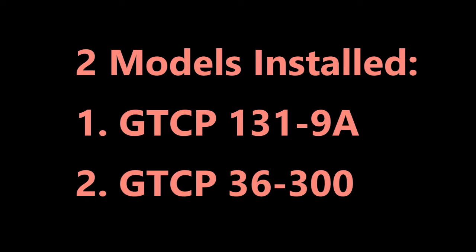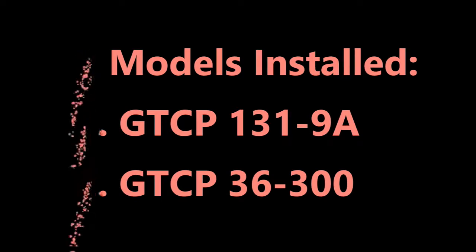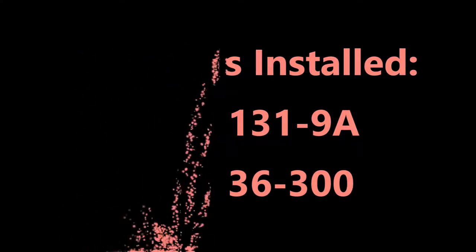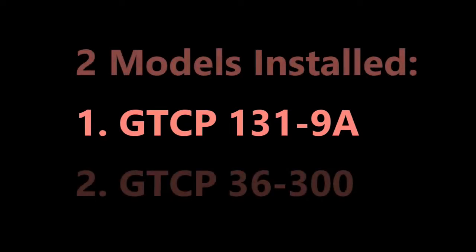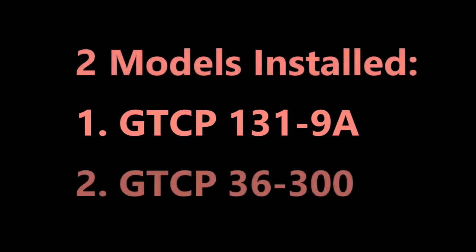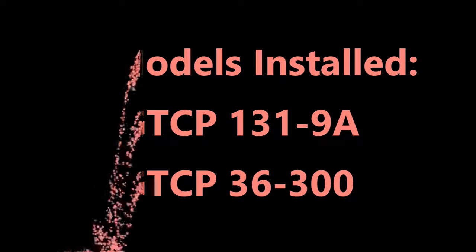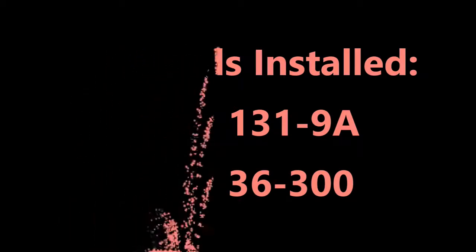And as far as the A320, it's actually installed on a certain range of variants on the A320. Okay, that's actually between 3270, I believe, and 3271 to 78. Those are actually shown on the airplane. So when you see those numbers, or see that it's a number within that range, then you'll know that the GTCP36-300 is installed in that particular plane.